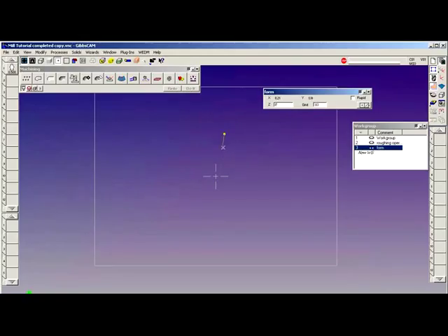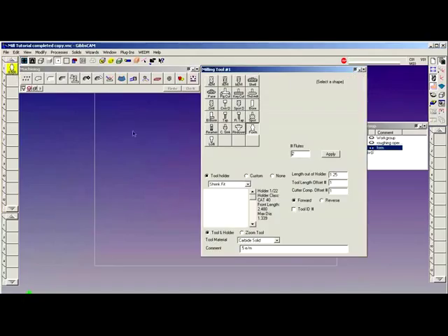I'm going to draw a shank and then come out here and draw a thread hob looking thing. Double click the last point and it will terminate the geometry. The rule for the geometry is that it must be terminated geometry, profile geometry. I then double click on it, open my tool tile, and come over to the apply tile, and there's my tool. Notice that the red plus sign determines where 0 was when I drew the part. Now this would technically be the touch off on my part.